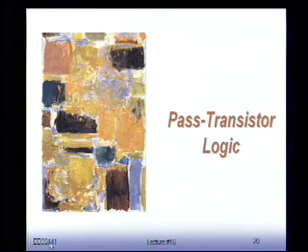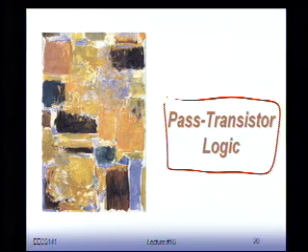New logic family. Pass-transistor logic. PTL. Again, this is a niche logic family. Not something you're going to use for every possible design. But for certain things, it is darn good. You go to our friends at Xilinx or Altera, the guys basically making programmable logic, FPGAs, they will tell you that they love pass-transistor logic. It's the easiest way to make programmable logic. And most of the stuff they're doing is all based on pass-transistors.